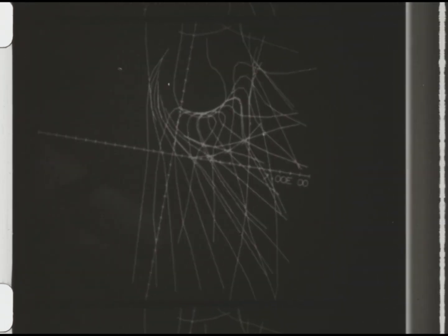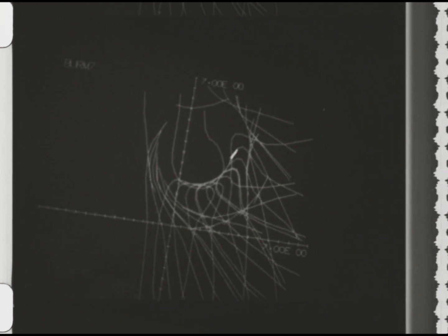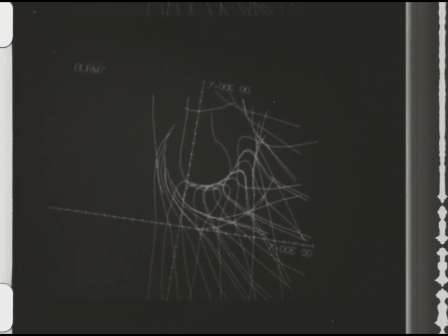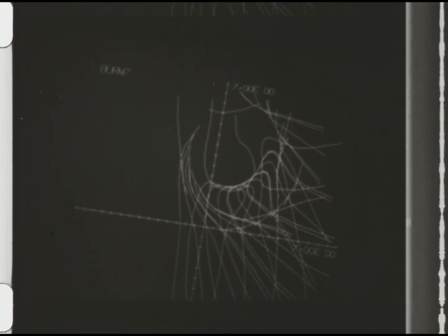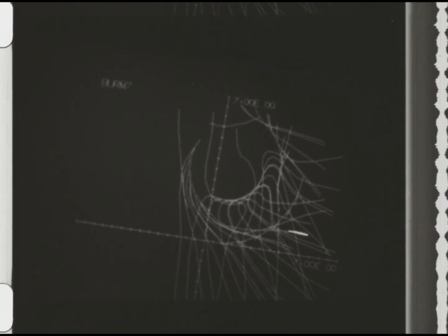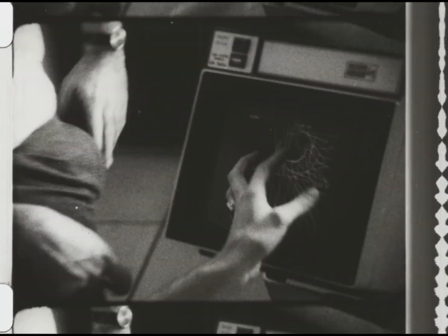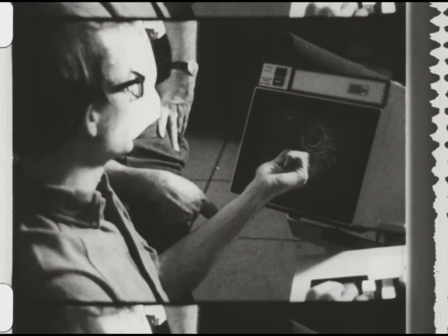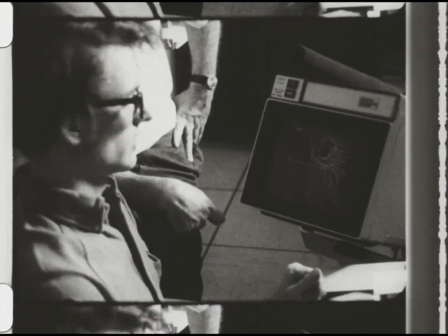In addition, one can make a great number of judgments as to the dynamic properties of a mechanism by studying the time sequence of these positions. For instance, you can look at the spacing on the positions and decide what are the velocities and angular velocities of the mechanism or of the body as it moves through these design positions. With this blow-up, one could, in between the design positions, see if there was any interference with the normal movement in this knee area. Let's go to the linkage and show that transmission angle.